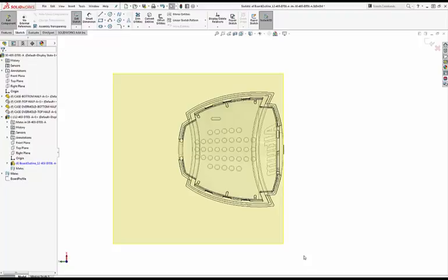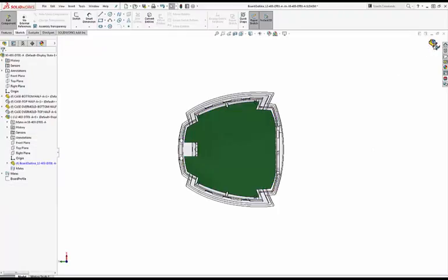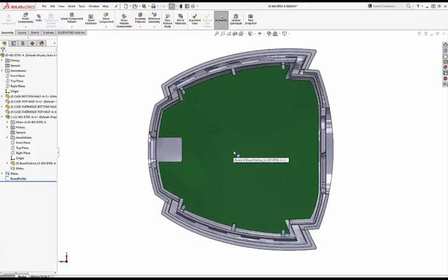We're going to edit the sketch to remove the extents of the board, retaining all of the board properties. Selecting the board profile, we're going to convert entities and change the extents to take on the shape of the board profile as defined within the assembly, and accept that.